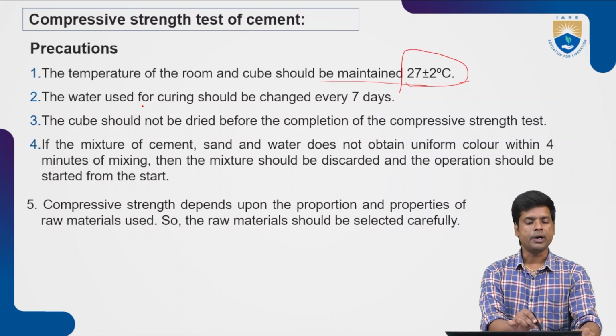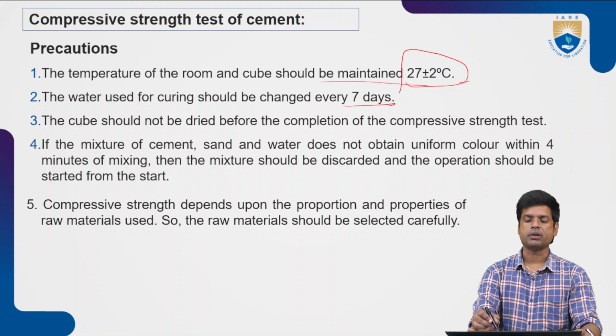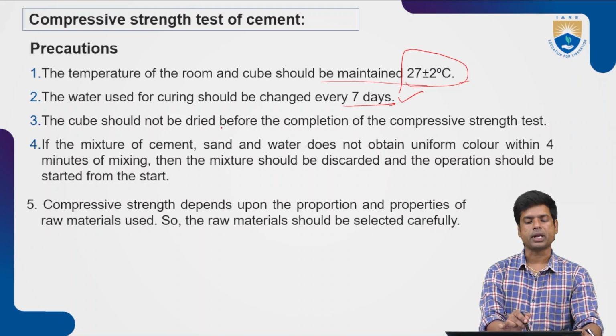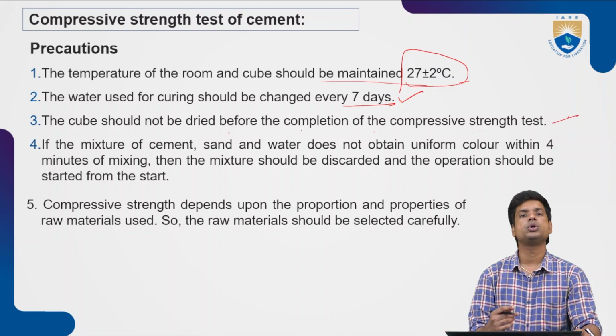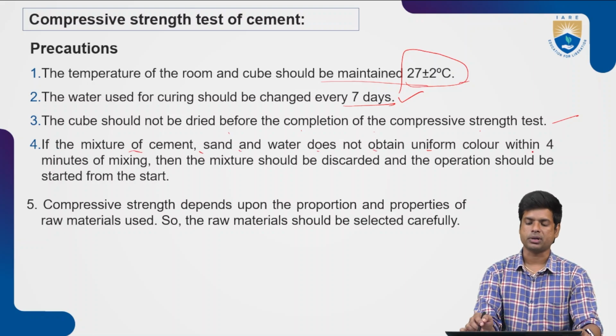And next one, the water used for curing should be changed every 7 days. So we are keeping it for curing for 28 days, right? So every 1 week, we have to change the water. And next one, the cube should not be dried before completion of the compressive strength test. So at any point in the curing period, that cube should not be dried. It should be continuously moist.